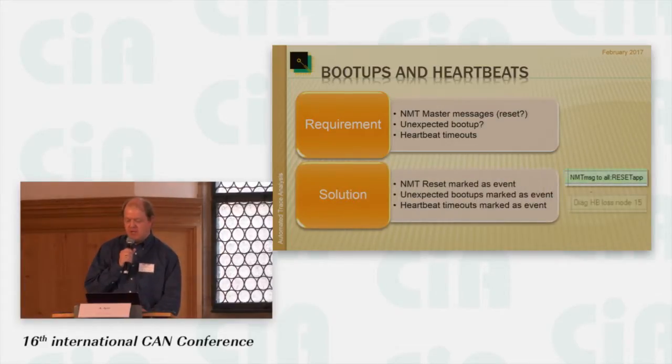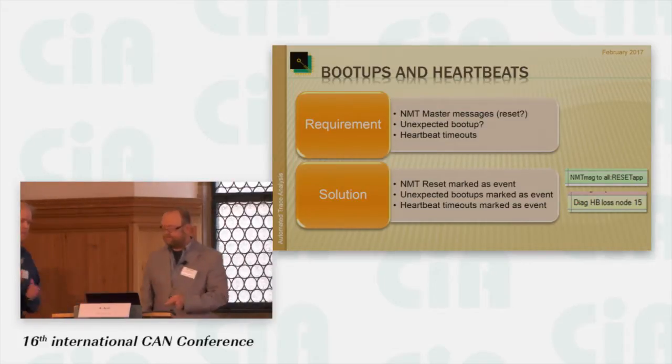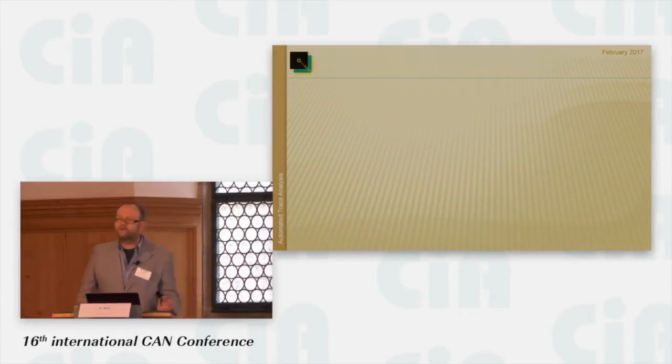It's also possible to detect boot-ups that occur without an NMT reset happening beforehand, perhaps indicating a spontaneous reset of the node. One important aspect that can be automatically measured is the time from an NMT reset to a boot-up message for every single node on the network. And by comparing the startup times, we can see if any of the nodes were unexpectedly slow and require further investigation.